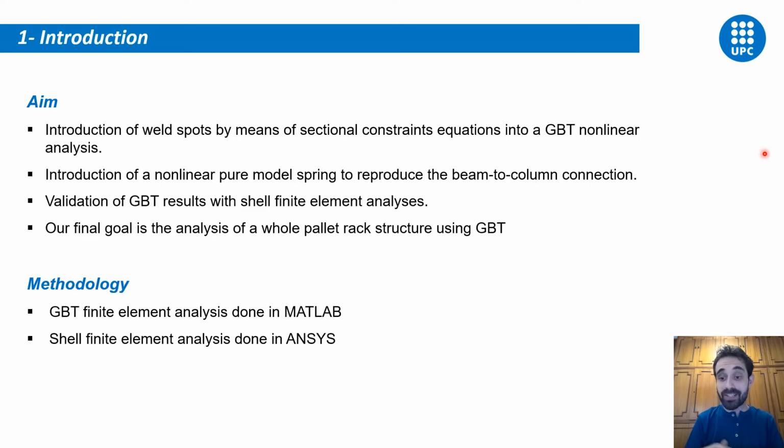So in order to reach this final objective, what we need to do is to solve the different particularities of pallet rack structures, like these ones here. All GBT analyses are carried out in MATLAB software, whereas the shell finite element analyses are done in ANSYS software.